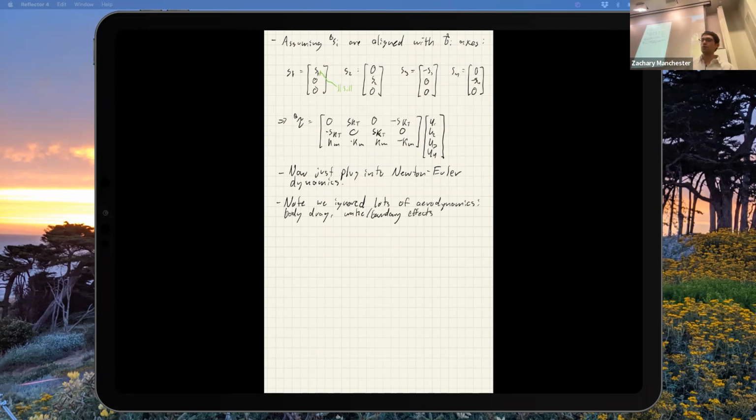It turns out with a quadrotor, for this model to hold, you actually have to be a meter-ish away from the floor. Say you have to be up high enough. In particular, this stuff starts to be a poor model when you go to land. You actually get way more lift than the model predicts when you get close to the floor. These start to matter.